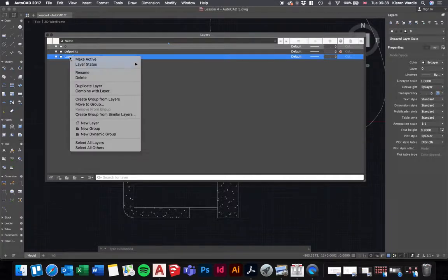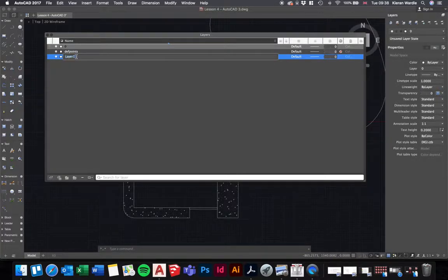So I'm going to rename this layer structure, but you could also just choose to say thick line. I'll do that instead. Thick line. I'll spell that correctly. So with the thick line, you can then choose the color by clicking on this little box, and you'll see here that AutoCAD has 1, 2, 3, 4, 5, 6, 7 default colors.